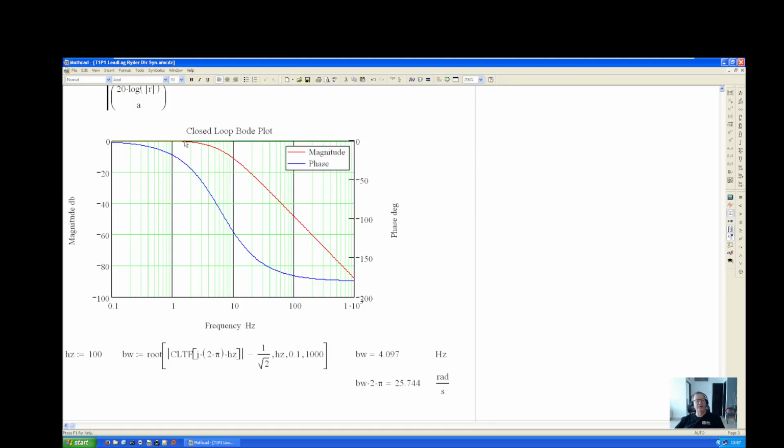frequency response of the motion is about 1.5 hertz because it takes 1/3 of a second to ramp up, 1/3 of a second to ramp down. The sum of those two is 2/3 of a second, and if I invert that, it's 1.5 hertz. So I'm actually running the system right in here, so there should be just a following error. And then the bandwidth is 0.4 hertz or 25 radians per second, which is much better than the original 20.